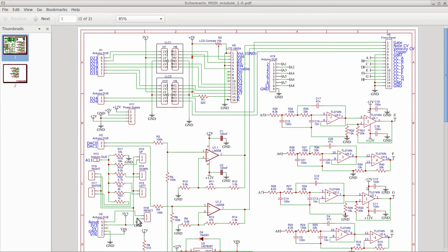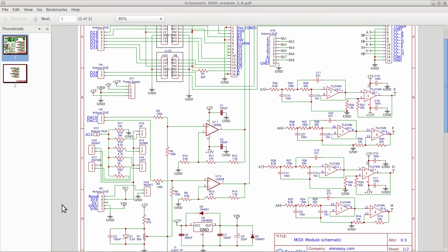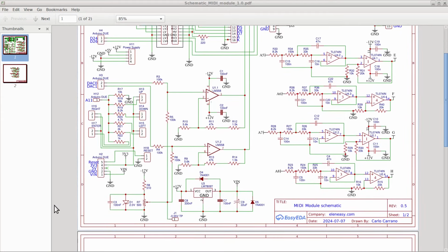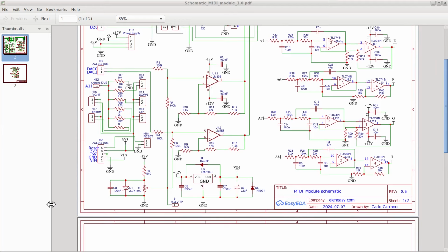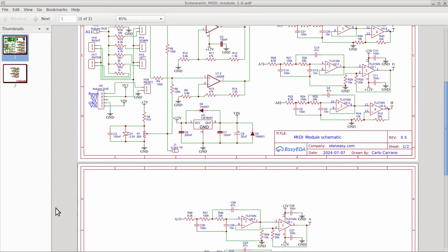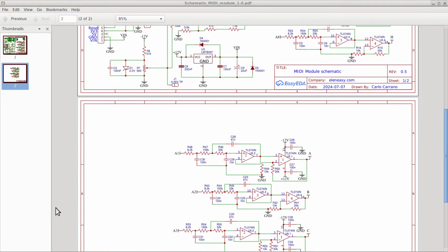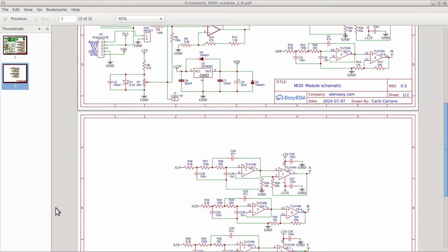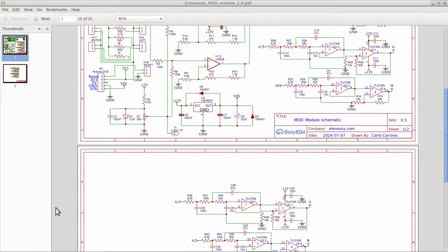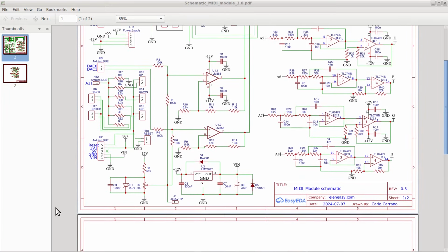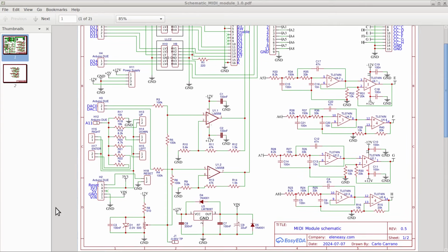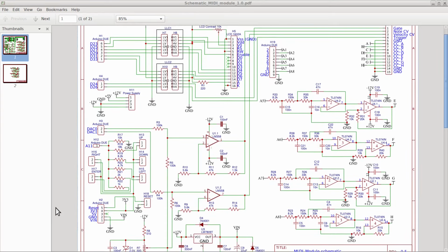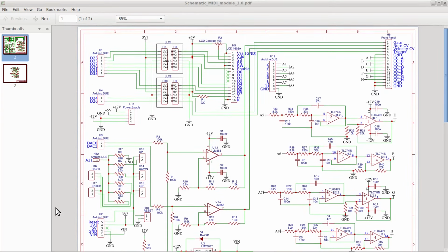Once all of that is done, the wiring is a very simple thing to do, because we only need to put DuPont wires between the pin headers on the PCB and the corresponding pin headers on the Arduino, or one of the boards on the back of the front panel. Just make sure to follow the schematic while you do so, and there will be no problem. If you find that some of the pins are a little loose in their socket, just thicken the pin by laying a thin layer of solder on it.